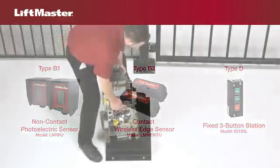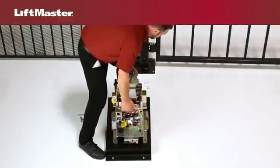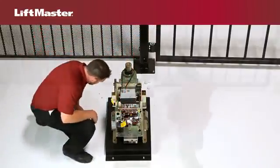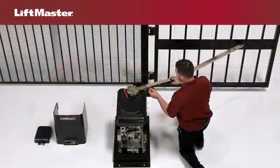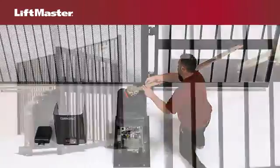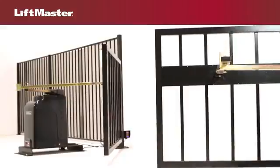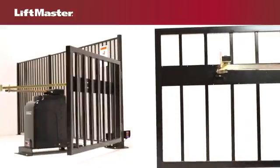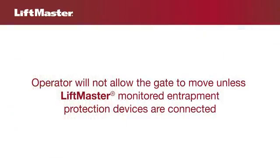The first, Type A protection, is already built into all LiftMaster gate operators. Simply installing our operators covers the need for one of the safety entrapment protection devices for both the open and closed entrapment zones. This built-in entrapment protection causes a moving gate to stop and/or reverse if it encounters an obstacle. Now we need to select a second protection device for each of the entrapment zones.